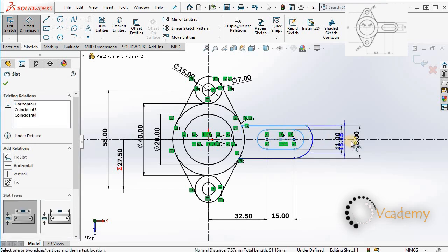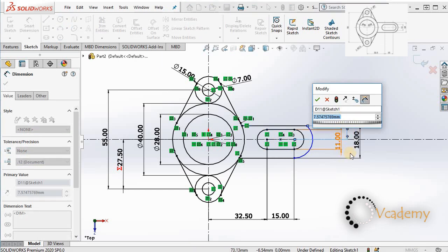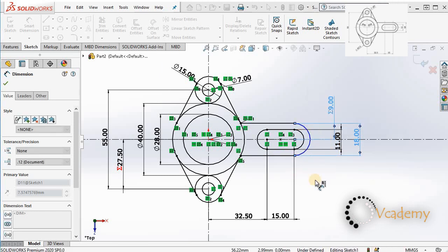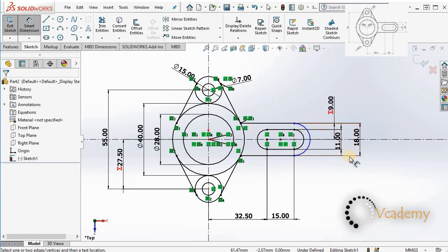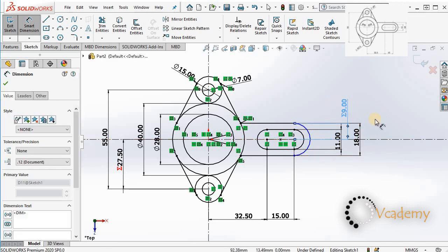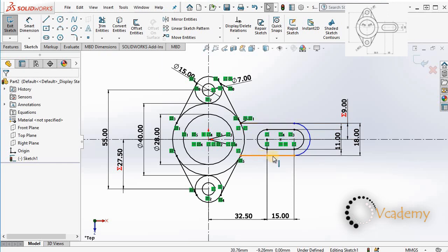There you go. And now again we use the formula there so that it's always half of your diameter here. So you say equal to, give this dimension, say divide by 2. There you go. Boom. And you have your dimension for that. This has become black. It means that it is fully defined now, this part, but not this. We can vary this, right?